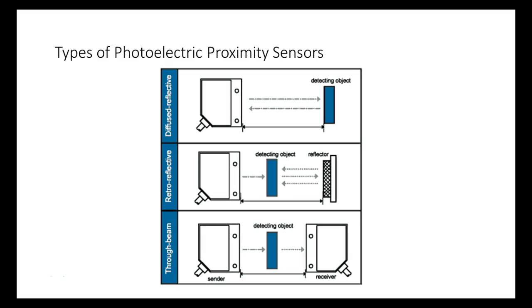So this guy's true all the time. If we look at the PLC, this light would be lit when there's nothing there. We come in, we break the beam, it'll go out. Right? You have to know that because of the way you write your PLC program, you need to know what the sensor gives you back when it's true and when it's false. So this is what we just demonstrated with this guy right here. And you've seen that demonstrated a lot of times.